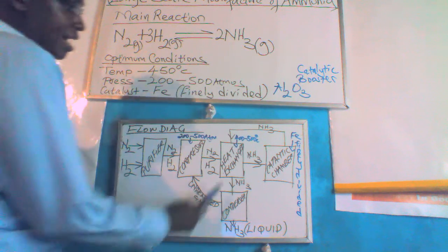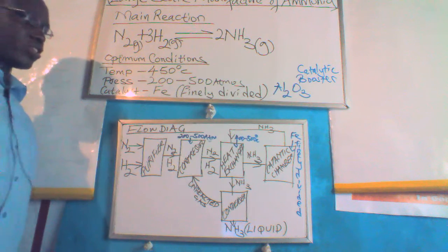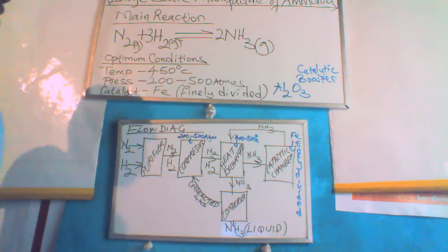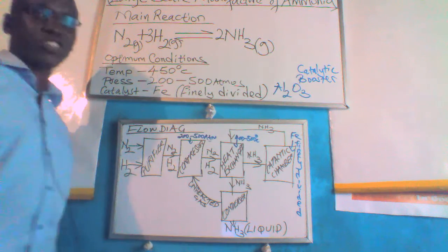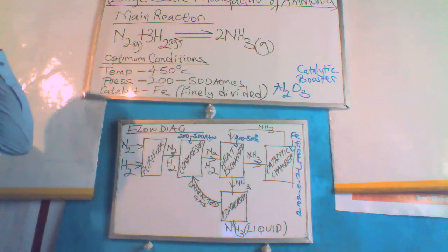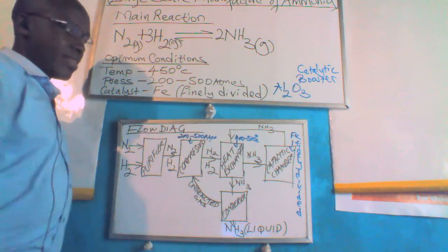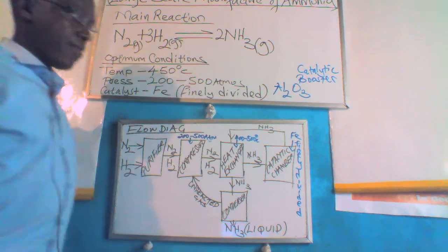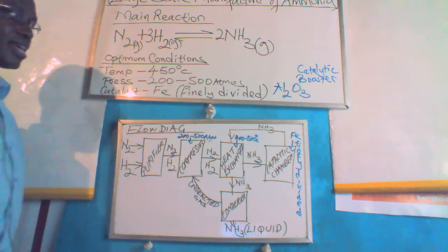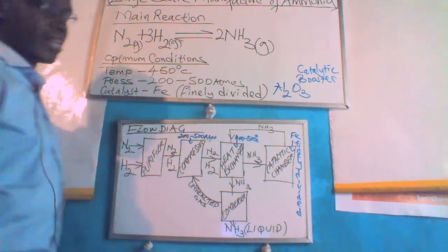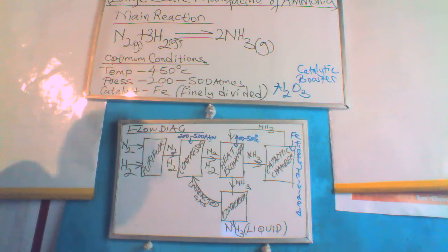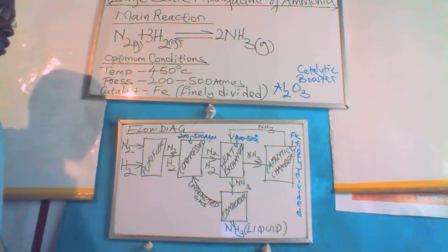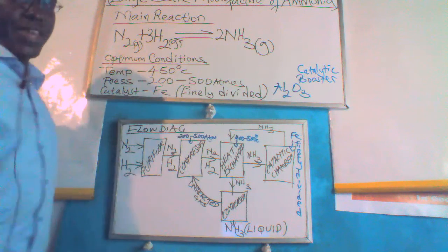Within the heat exchanger, there is an interaction or effective reaction between nitrogen and hydrogen gas, which converts them readily into ammonia gas. However, since the reaction is slow, there is a catalytic chamber which is intertwined with the heat exchanger. Within the catalytic chamber, finely divided iron impregnated with aluminum oxide is added, and that speeds up the rate of reaction such that the ammonia gas formed yields roughly 90% conversion of nitrogen-hydrogen into the required gas.